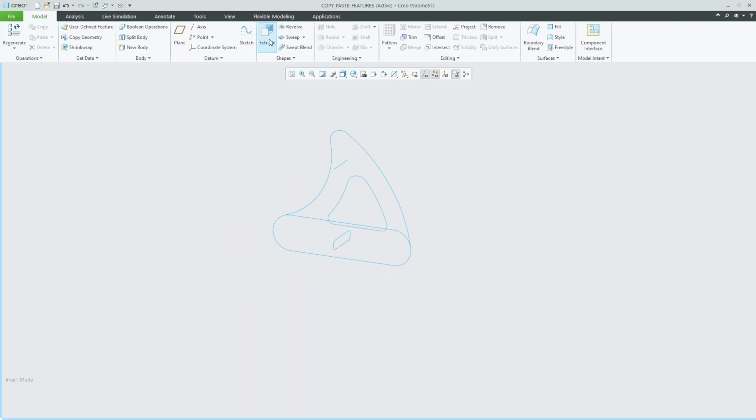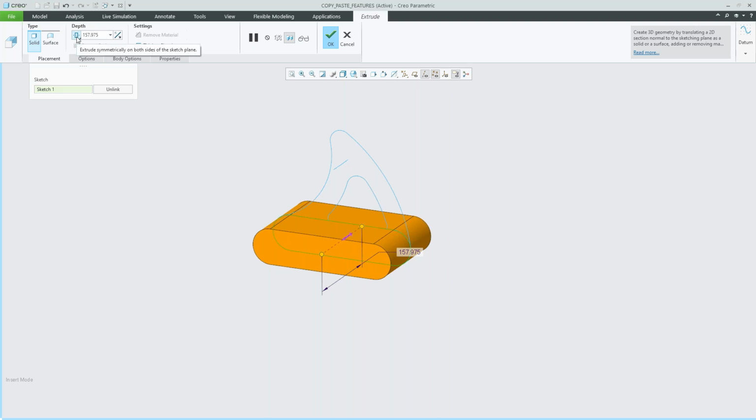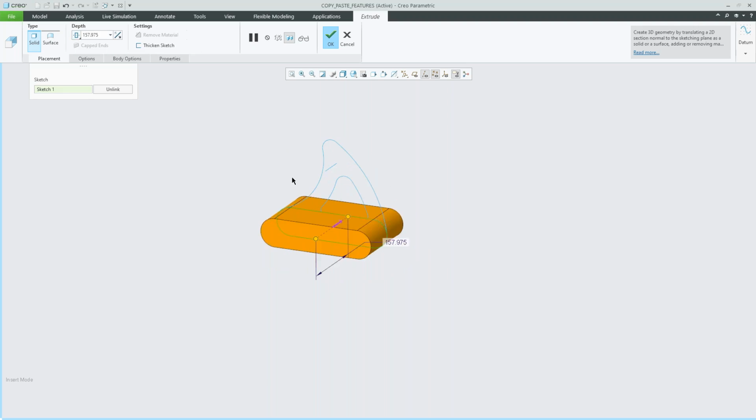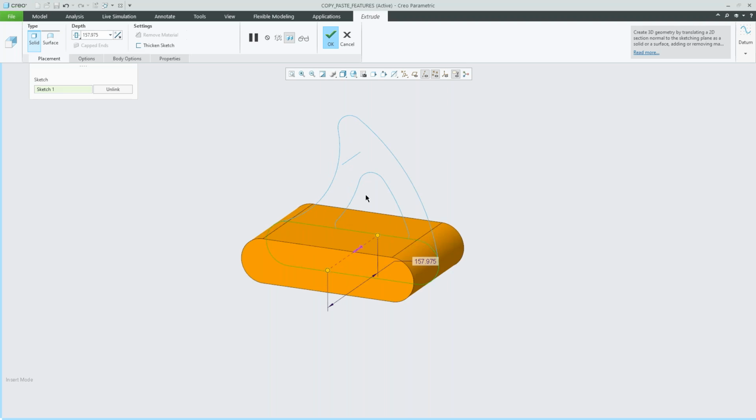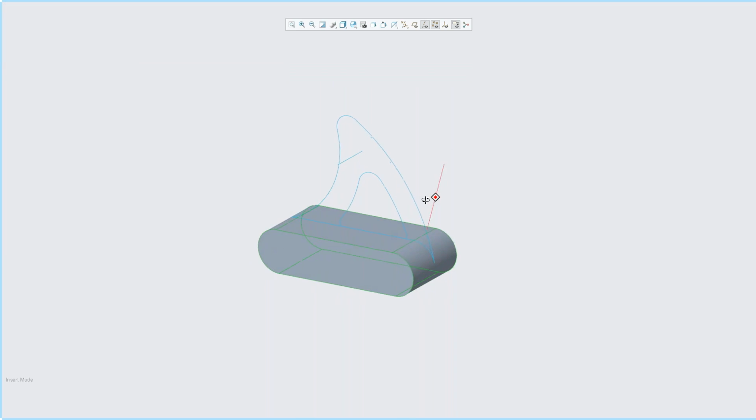Now, let's say the first thing I do is extrude. Let's select this one to extrude. And once I do that, I have these quick commands, these quick access windows which pop up right here, and I can use these rather than going here and changing my depth options and so on. I can directly concentrate on my sketch here. So let's maybe change the dimension here. See, I do all these things on my screen itself, and then hit enter so that the feature is created.